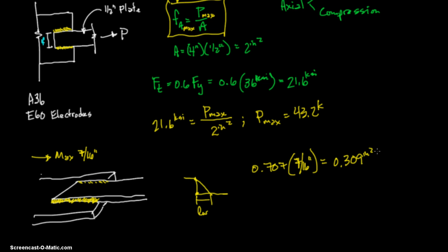times the allowable, what is the allowable stress of this weld. And to figure that out, you go to page 570, and it says allowable stress on welds. We go down, we don't have a complete penetration groove weld, we don't have a partial, we have a fillet weld. So I would say that it's shear on effective area. Sure, we're shearing. It's going to shear this. And then it says 0.3 times nominal tensile strength of weld metal. And then over, it says required weld strength level. Weld metal with a strength level equal to or less than match weld metal is permitted.